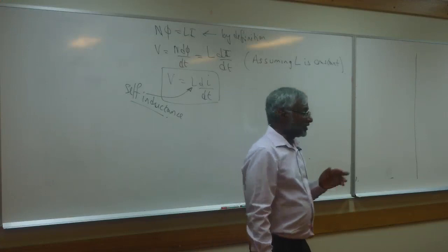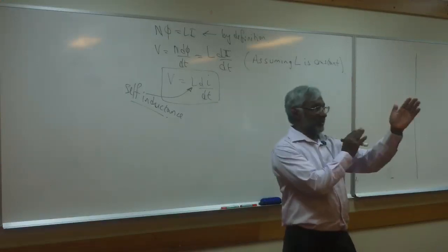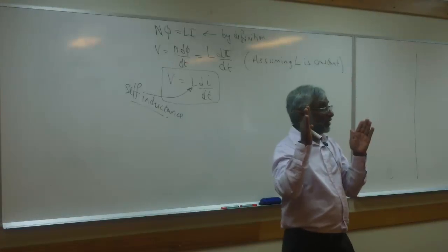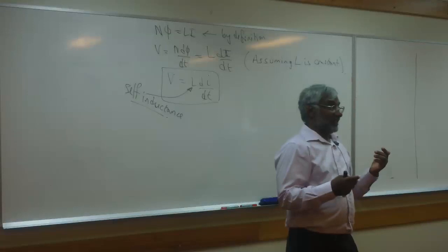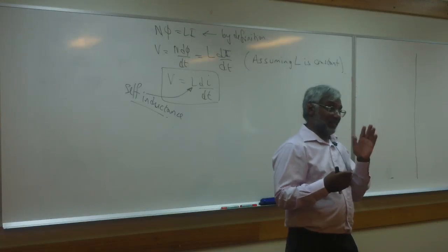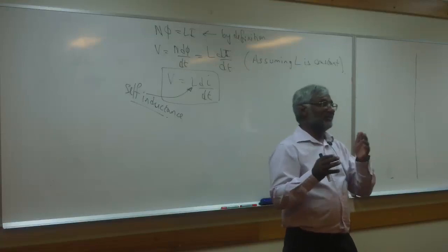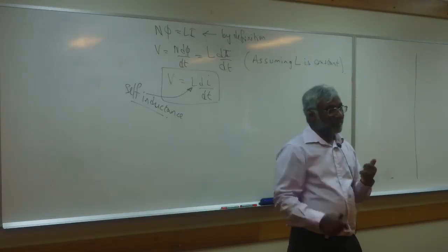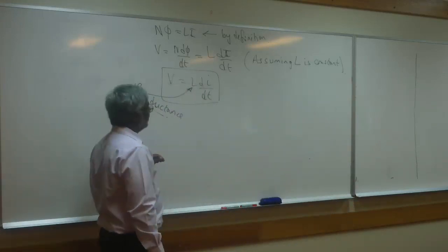And the reason mutual inductance plays a part is you have one transmission line that you're trying to protect, but there is another transmission line close by, and many times they're on the same tower, and that would have an influence. So one line has an influence on the other. So there's mutual coupling between them. So we have to introduce the idea of mutual inductance.